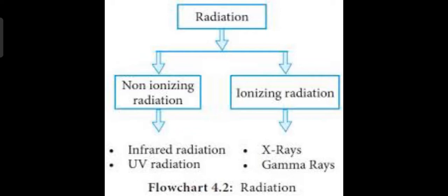Disadvantages of using UV rays are they have low penetrative power and the UV bulb has a limited life. Some bacteria have DNA repair enzymes that can overcome damage caused by UV rays. Organic matter and dust prevent its reach. Rays are harmful to skin and eyes also. It doesn't penetrate glass, paper or plastic.